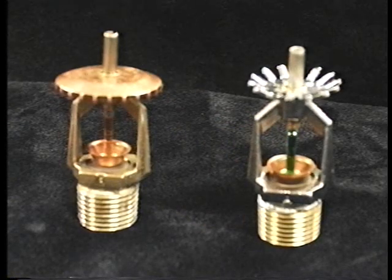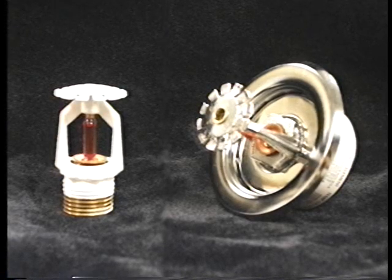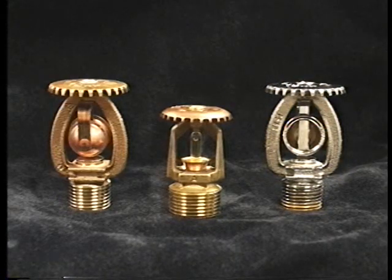A quick response sprinkler system is one that meets certain response characteristics for responding to fires more quickly than the typical sprinkler. A recessed sprinkler is installed so that a portion or all of the sprinkler body is mounted in a housing recessed into the ceiling. In this arrangement, the sprinkler is installed in the pendant position. A pendant sprinkler directs the water spray downward towards the sprinkler deflector, while an upright sprinkler directs the water spray upward towards the sprinkler deflector, effectively distributing the water stream.